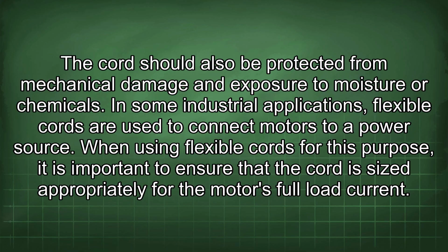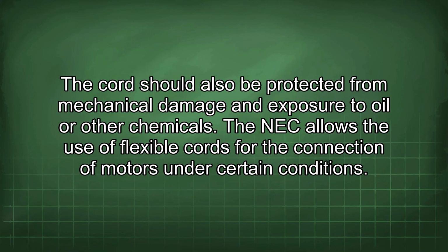In some industrial applications, flexible cords are used to connect motors to a power source. When using flexible cords for this purpose, it is important to ensure that the cord is sized appropriately for the motor's full load current. The cord should also be protected from mechanical damage and exposure to oil or other chemicals.